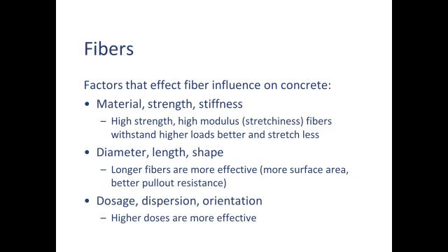With GFRC, I'm going to touch on it in a minute, but it's important to use a certain amount to get the kind of properties. Otherwise, you're just dealing with a brittle, non-aggregate based mortar mix if you don't have enough fibers in it.